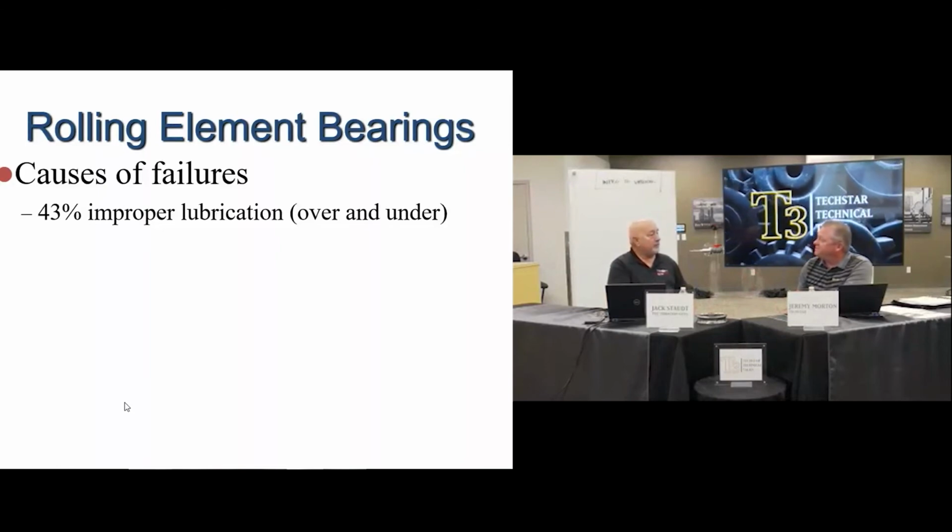I'm seeing some issues now because a lot of these facilities are using ultrasound to grease their bearings. So they have an ultrasound system, pump some grease, you can hear it lower, and you've got the right amount of grease. But they're not following the OEM recommendations on the frequencies you should do it.